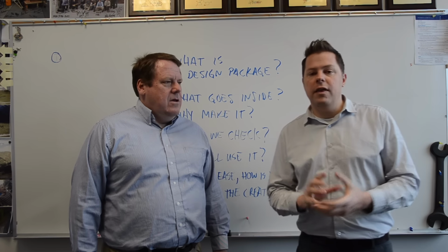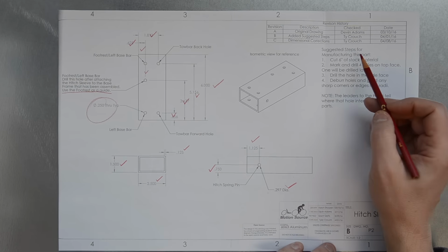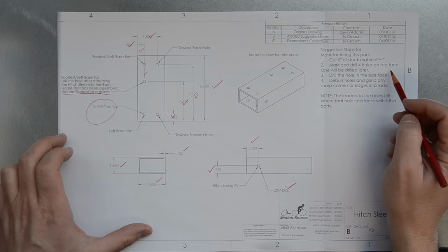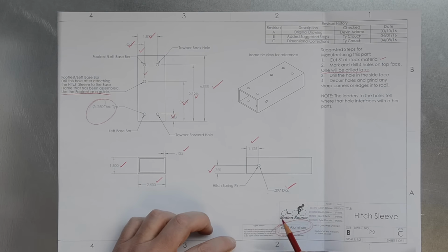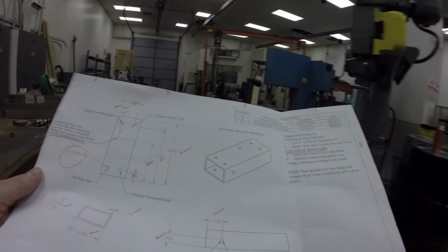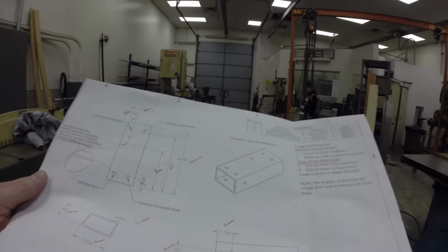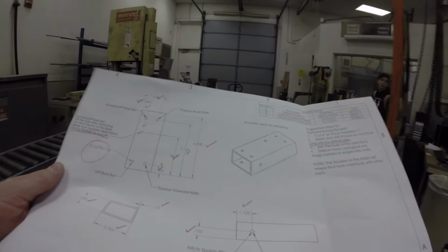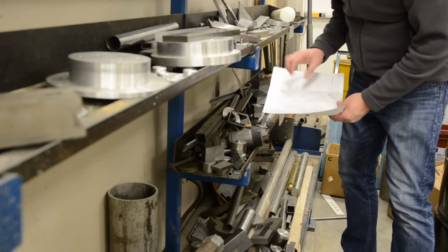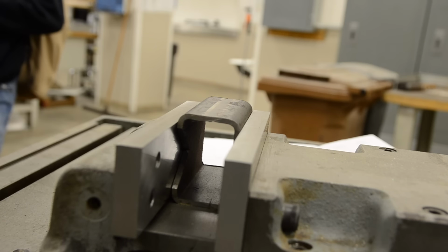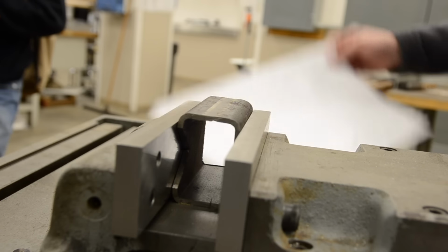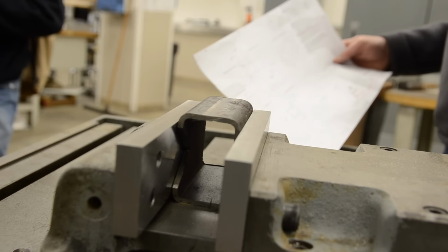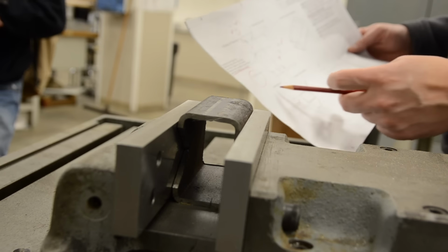All right, next thing that I think really helps with this kind of thing is to imagine yourself using the information that you're checking. So for example, if you're checking an engineering drawing, you might take that engineering drawing in your hand and you might envision what would happen if you went into the machine shop. Would you know what stock to get? Would you know how to start making the cuts and where the cuts would be? And if you look at the features of the product, would you be able to determine the depth of a channel or the depth of a hole or the diameter of a hole or whatever it might be? And doing that, you can often find some problems.